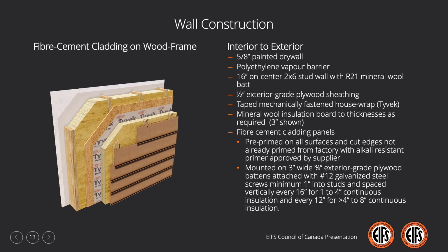This allows for the holding of the insulation without the use of additional securement methods such as impaling pins or other fasteners that may contribute to thermal bridging and heat energy loss. This method is optimal and provides for only 2 to 6% degradation, and the battens provide a good solid nailing surface for cladding to be attached to as well.